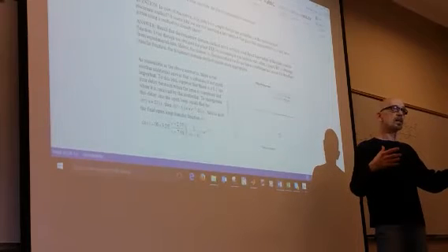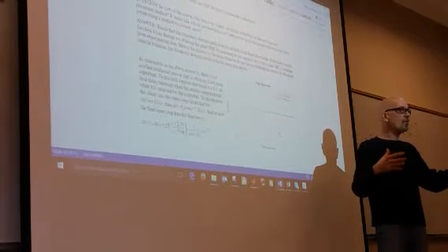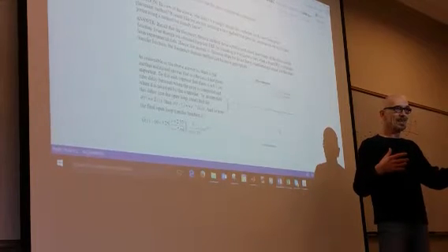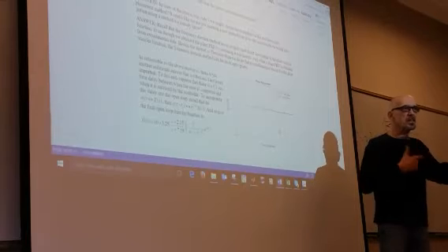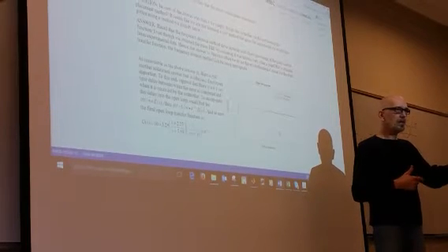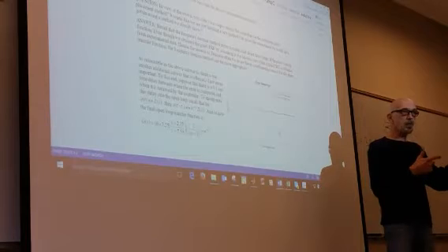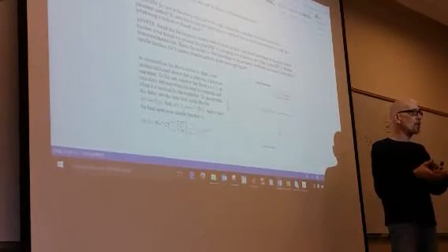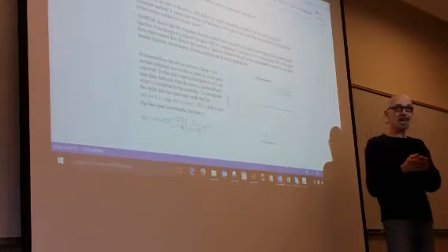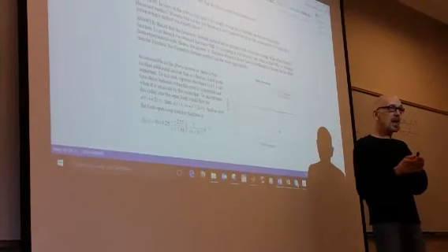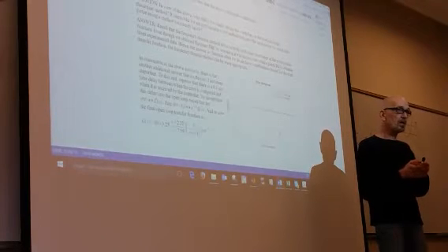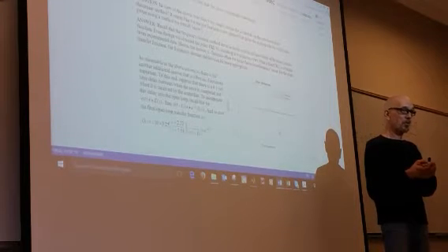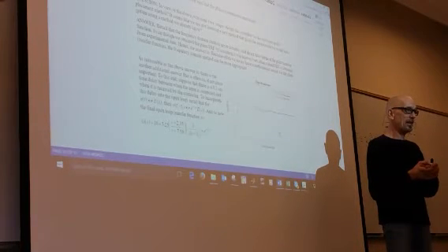How do you get 1/10 of a second delay? Well, you have a really cheap processor that's doing 20,000 other things, multitasking. And so it says, yeah, we only need to do this every 1/10 of a second, right? Every 1/10 of a second will be fine because we're doing lots of other things with this little processor. So even if it's on board, you, as a systems engineer designing, they may not think that time delay is going to be a big deal. But you can tell them, no. In feedback control, time delays can be death.